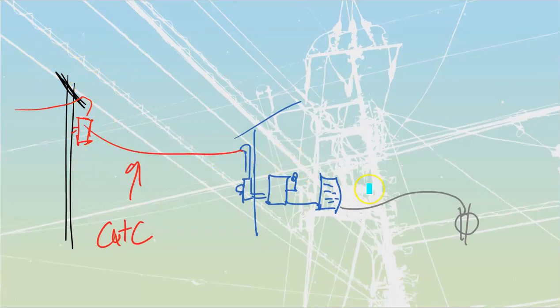Remember that as we go further and further through our system, and especially as our wire gauge goes down, we're going to see more and more counter EMF or inductive effects that are going to prevent surges from getting all the way through. So we've got our category C out there. Then we're going to have category B, which is going to be for feeders and distribution. Category B is going to be everything that is inside of blue over here. That's my category B.